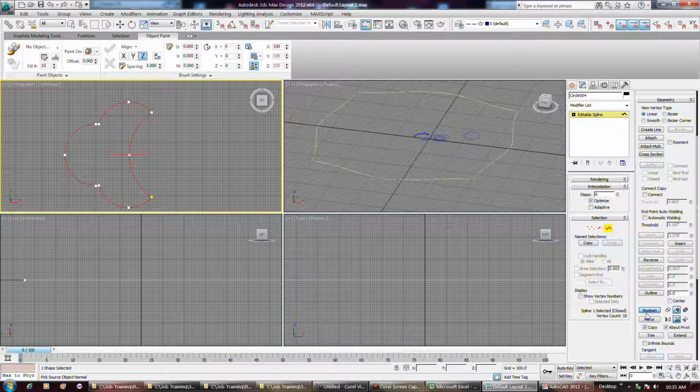And by the way, I didn't have to actually stop out of it to switch modes. I could have just switched to subtraction mode while Boolean was still engaged. In fact, I'll show you again, just to make my point. We got our first one selected, set it in union mode. Then we add these two, but I can now put it into subtraction mode, and voila. And then stop out with the right mouse button.